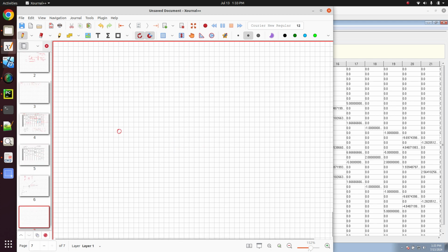So we're dealing with beam elements. So this adds stiffness to the following degrees of freedom. So here, for translation, it adds stiffness. For rotations, it adds stiffness. So here, these are checkboxes saying that it adds stiffness to those degrees of freedom.